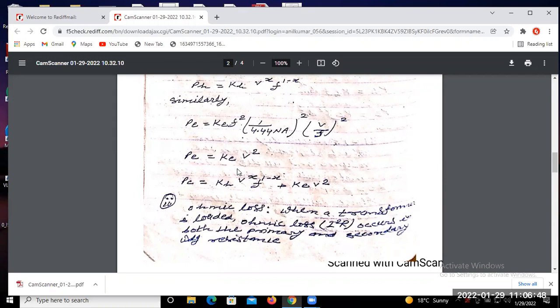तो जस्ट इसको लिखो मैथमेटिकल इक्वेशन में, लॉसेस में हम लोग कंसीडर कर चुके हैं कोर लॉस, ohmic लॉस, उसका वैल्यू लिखो एंड आउटपुट पावर वी ऑलरेडी एक्सप्लेन दैट V2 I2 cos थीटा 2। एफिशिएंसी इक्वल टू कितना लिख सकते हैं, आउटपुट पावर दैट मींस V2 I2 cos थीटा 2 डिवाइडेड बाय आउटपुट पावर प्लस लॉसेस दैट मींस V2 I2 cos थीटा 2 प्लस लॉसेस में क्या हो जाएगा, कोर लॉस दैट मींस P सफिक्स C एंड ohmic लॉस दैट मींस I square R इक्विवेलेंट। तो जस्ट राइट इन मैथमेटिकल फॉर्म फॉर द एफिशिएंसी ऑफ द ट्रांसफार्मर।